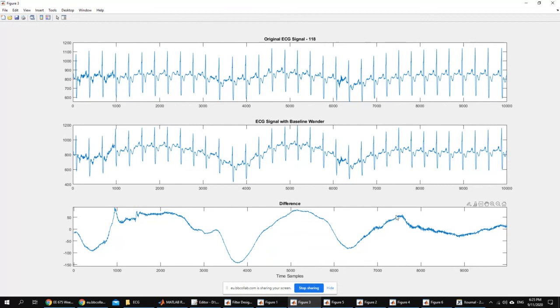I estimated roughly what the frequency of this artifact is like. I basically estimated the distance between this and that. But actually, you can try something different. You can actually estimate the difference between this and that, the location here minus the location here, okay? And see exactly what happens, okay? So basically, from this crude estimate, I started designing a filter and started experimenting with this filter.